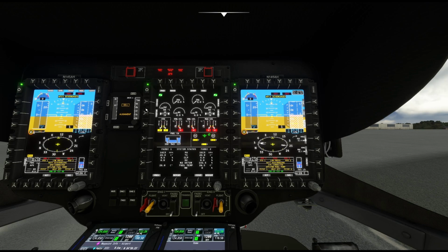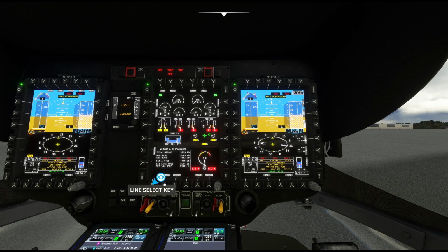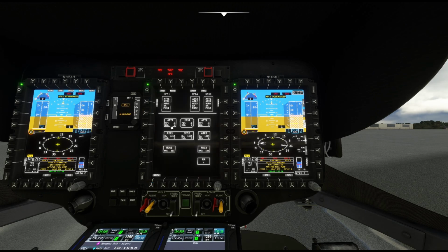Interestingly, also, if we go over to the reconfiguration page, we'll notice right here that the IESI has its own pitch and roll sensors inside of it, fiber optic gyros. It also has its own air data inside of it. So air data computer 1 is pulling this information, indicated airspeed, and the ambient pressure, which we'll notice 1013 is the raw pressure, which matches 1013 being read by the FADEC. All right, which is also the same as being read by the air data computer inside of here. So the IESI has both of those.